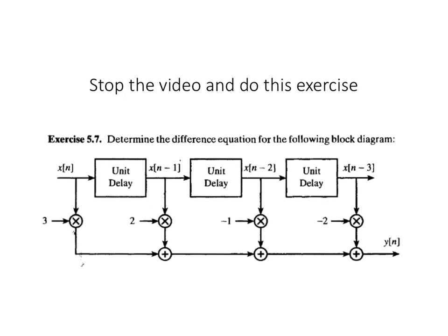So to get a little practice in that, here's another block diagram, an exercise from the book, in which it's the same length of filter, a three-element filter, three taps, three coefficients, actually four coefficients. So go ahead and take a minute, stop the video, and write down the equation for this block diagram, and then start the video up again.